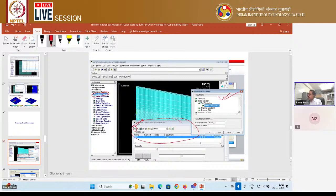Here, let us consider we want to see the nodal temperature data. If we click on nodal temperature, an arrow will come. Based on this arrow, we need to select any node. Let us consider we want to see the center line node, and how the temperature distributes over time at that center line. Similarly, for any other location we want to see the temperature data, we can get it using this window.